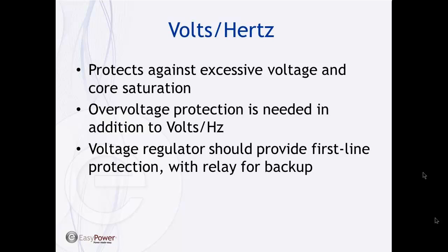Again, as we mentioned with the excitation system, the voltage regulator should provide protection against volts per Hertz and overvoltage, undervoltage, but the protective relay will be used as a backup to the voltage regulator. Overvoltage settings may also be dictated by your transmission operator or your utility, and so that's another factor that you have to put in there.